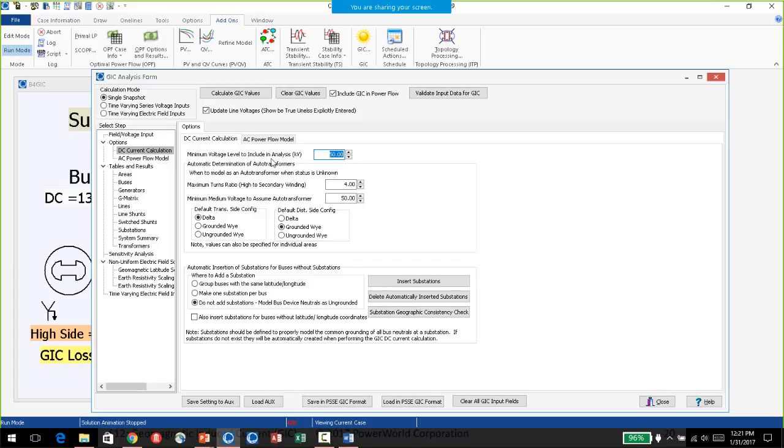Scott, if I might just for a moment speak to that, I completely agree with your viewpoint. I would point out that PowerWorld did a study on this for Avista, what was it, 4 or 5 years ago. Subsequently we licensed the software, did a study, and helped EPA do their study. I can tell you what our system does: our 115 and 230 system nicely sources GIC to Bonneville's 500. If you were to exclude our 115 system, and we tried it, you get a much different answer. It's wrong.